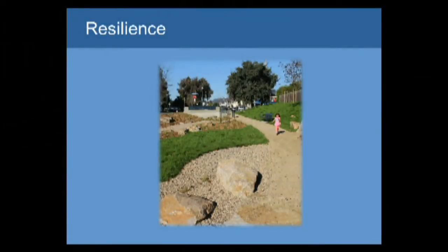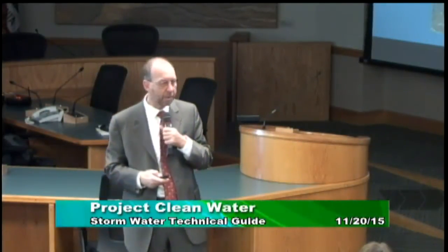Is it a concrete wall? You can see the slopes coming down on the side, and then the feature up towards the stop sign there is a head wall. That really provides the drop-off from the adjacent sidewalk and the arterial street. Another thing is the bottom doesn't look flat, but as we'll find out later, I made sure this thing was built flat. So its appearance isn't flat, but the bottom of it, you can see the runoff fills it right up. So, a nice, attractive kind of community feature. And this one drains streets, but on a larger development, you could have a private developer build something like this.